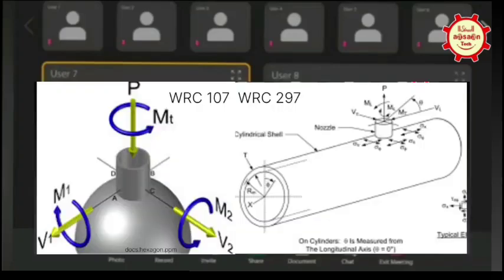Second, in case the piping load is very high, which the equipment nozzle cannot take, then in such a case, how do we mitigate such a problem? Because piping people are saying that they cannot reduce their load, and the static equipment vendor is saying that even we cannot increase our load. This is the situation at present. But first my question is WRC 107 and WRC 297. Do we have to do it every time?